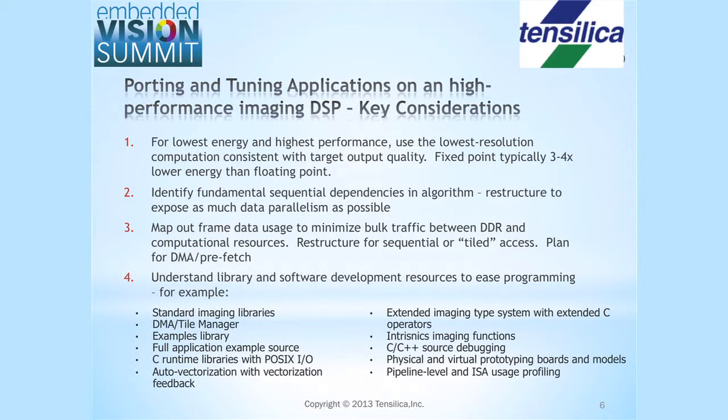That clearly isn't going to work in most platforms which have finite memory resources close to the computation. And so you're really going to need to think about how that gets restructured for tiled access so that you can bring in a pipeline of chunks flowing in as a stream, typically of 2D tiles, exploiting either cache prefetch or DMA resources to hide that.